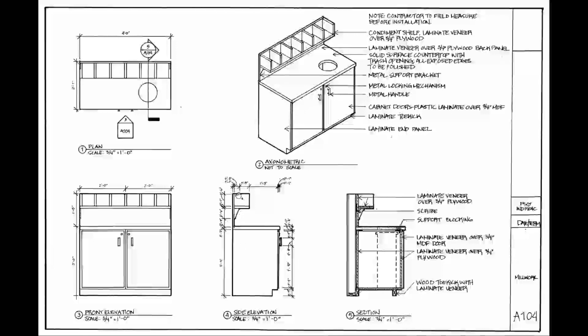You can see here, I had the same issue, right? So there was a very small dimension here, just 1 inch, and then 3 inches, neither of those fit. So they had to be pulled out and are stacked on top of each other. So that's how it's handled. Sometimes there's just no way around it, but you have to be really careful. Use your thinnest line weight here to create your dimension lines and your dimension numbers, and just do the best you can. You can see here with this side elevation, same deal.